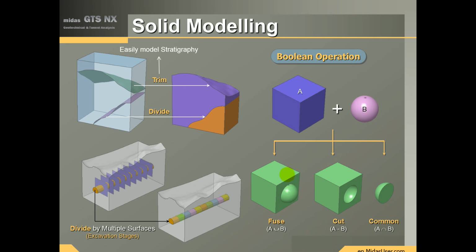For solid modelling, you can either use predefined solid shapes to create volumes, or build up your own using 2D geometry features. Solids and other geometry entities such as surfaces or edges can be automatically combined, with operations such as Boolean, dividing solid volumes for construction stages, or generating ground layers.